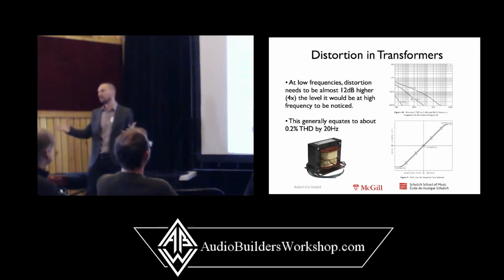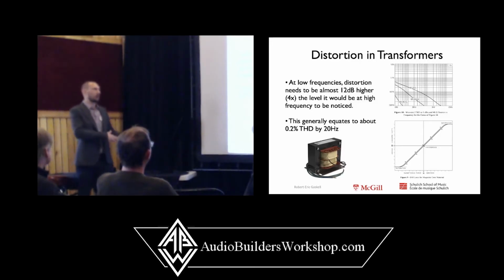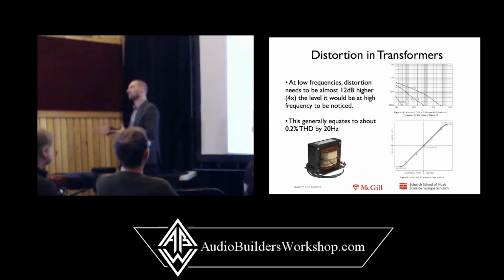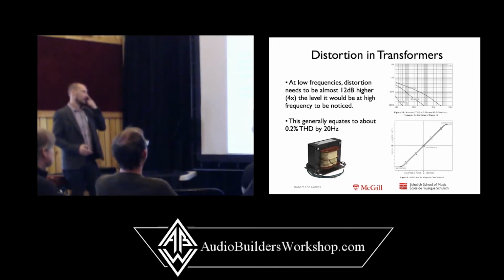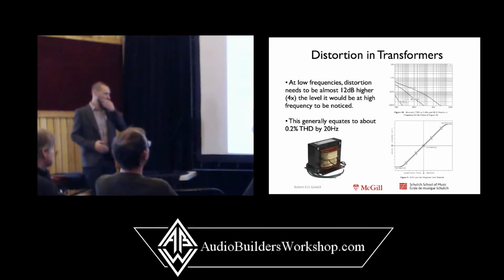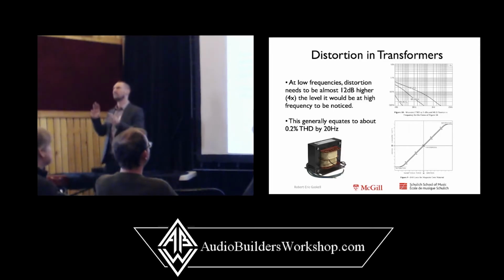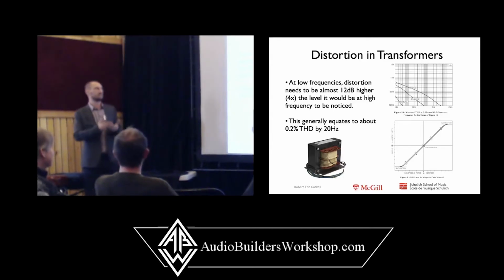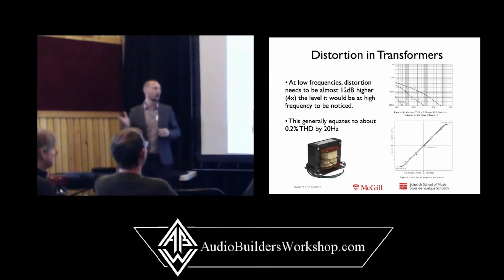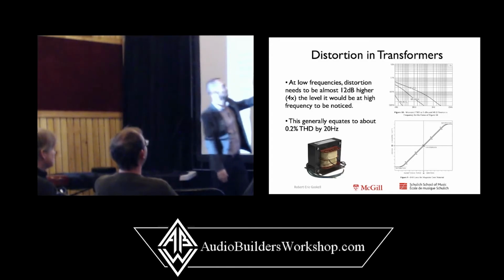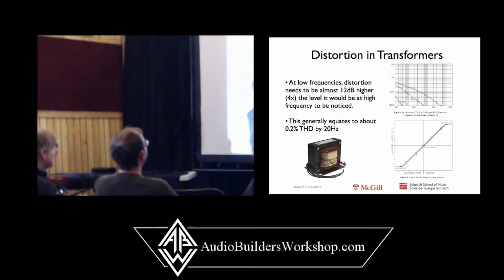Transformers are where we get the low frequency distortion from. Capacitors too, but transformers are much more nonlinear, although people seem to think that they're nonlinear in a pleasant way. Whereas capacitors get blamed for poor audio quality, people seem to like the distortion that transformers create at low frequencies. Derek was actually showing me a product that he has that allows you to switch between different types of transformers, like steel or nickel or iron.